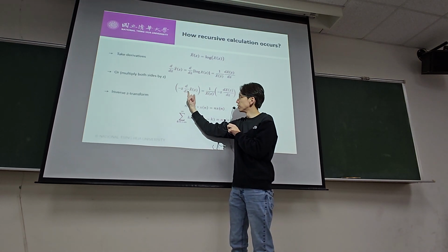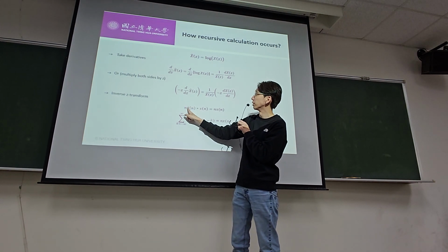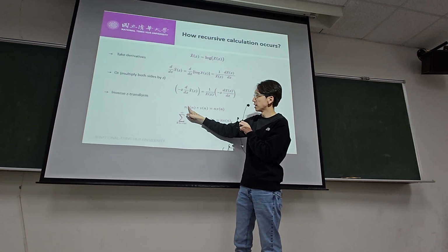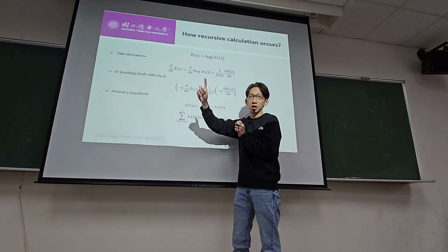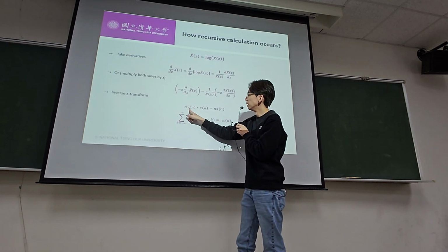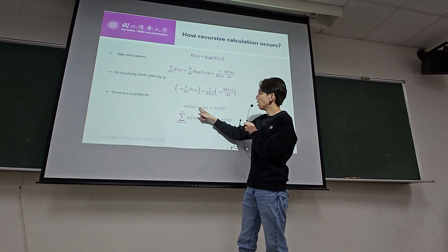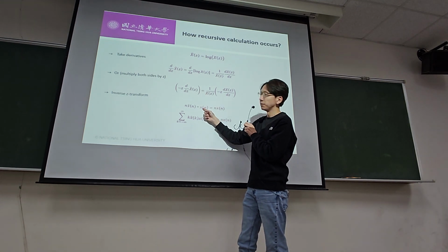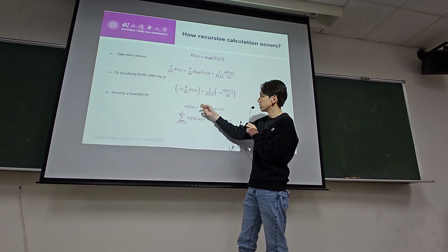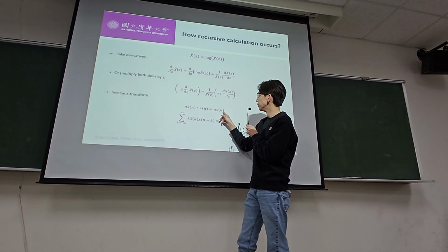We know the inverse transform of x hat of z is x hat of n, the actual complex cepstrum. The inverse z transform of those two terms multiplied becomes a convolution, so convolving with x of n equals n x of n.